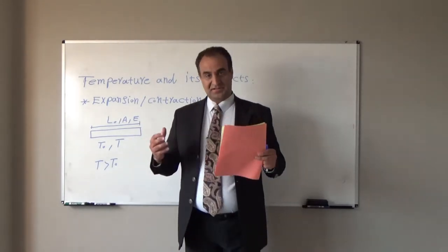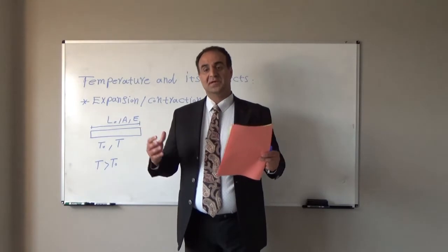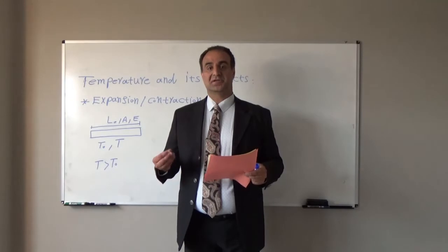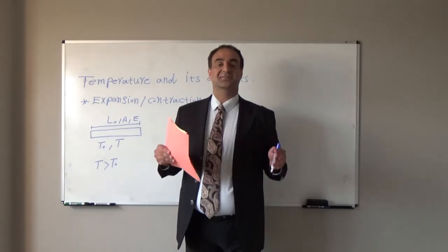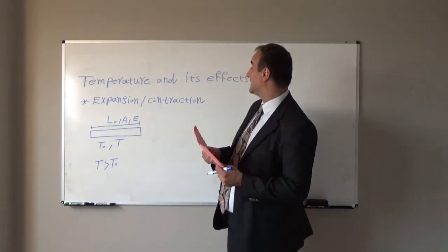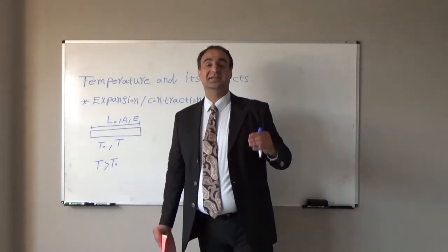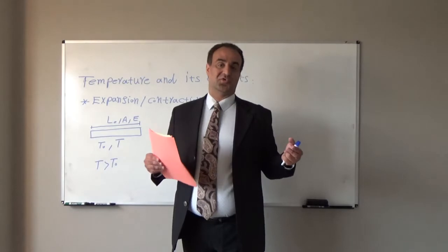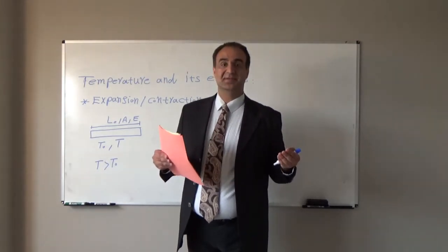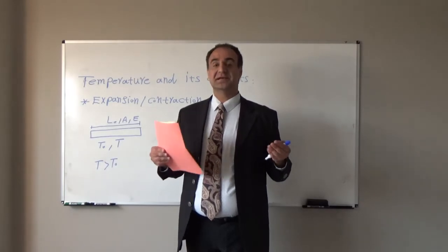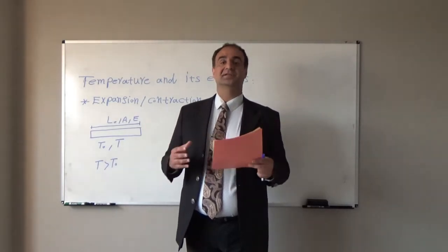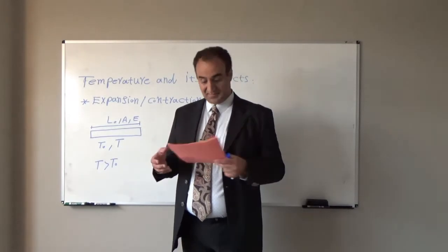Any material that is free to deform, if we increase temperature or decrease the temperature, we will see deformation. But we will not have any internal stress inside of the material because of the temperature effect. But if it is not free to deform, in that case we have another story. In that case we will not see any deformation or size change. But instead of that, we will have internal stress inside of the material.